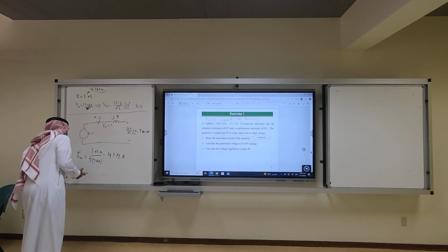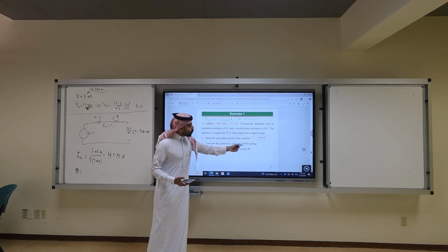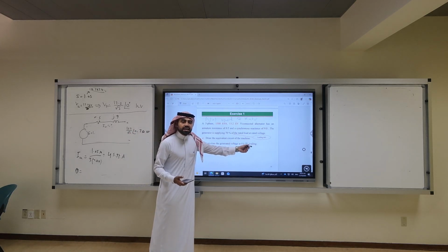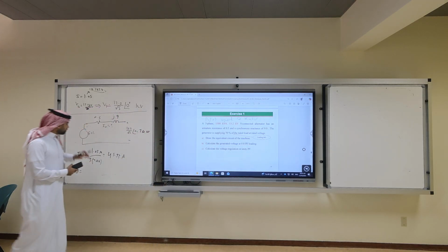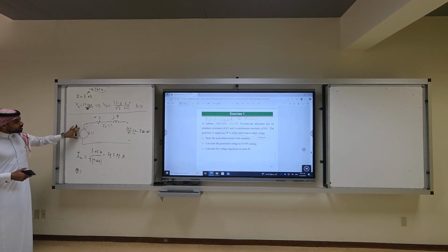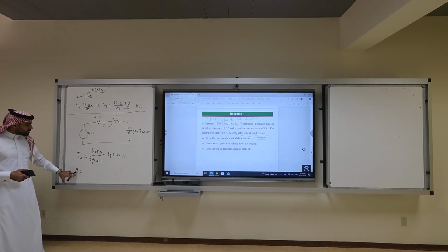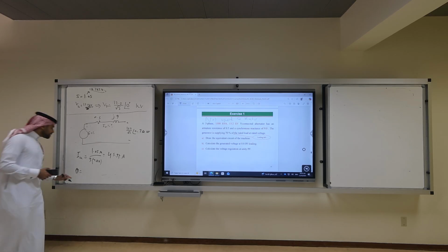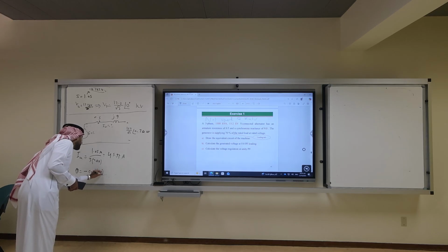So what is the theta? It's telling you calculate the generated voltage at 0.8 power factor leading. So to get EA, the generated voltage or induced voltage or excited voltage, which is not the terminal voltage, I need IA. To get IA, I need its magnitude, but also its angle. So what is theta? Theta is minus cosine inverse of 0.8 because this is leading.